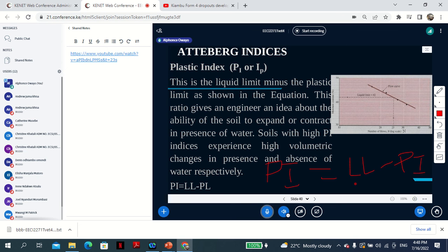If that's the only soil you have and it's on a thick layer, then depending on the structure, the only thing you can do is pile foundation. But if you want to do pad foundation, all these shallow foundations, the mat and so on, in most of the reports I do for clients, I say the lucky bit is in Nairobi. Unless you are talking about certain isolated parts of Eastlands, it's fine.